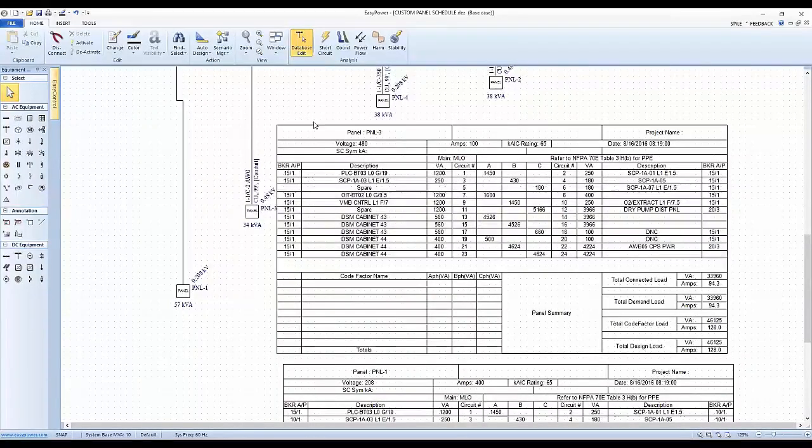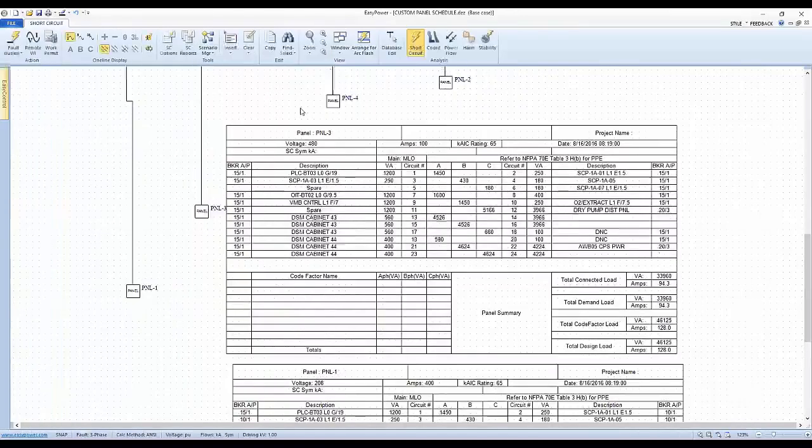The way I get data into these new variable sockets that I've built is I need to go to short circuit focus. Again, my one line needs to be clean to be able to do this. Under fault the buses, everybody pay attention because this is the tricky step. I'm in short circuit focus.